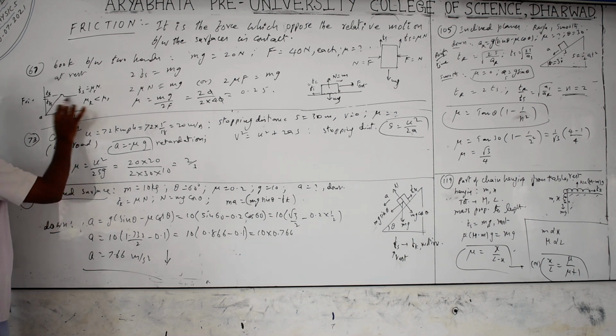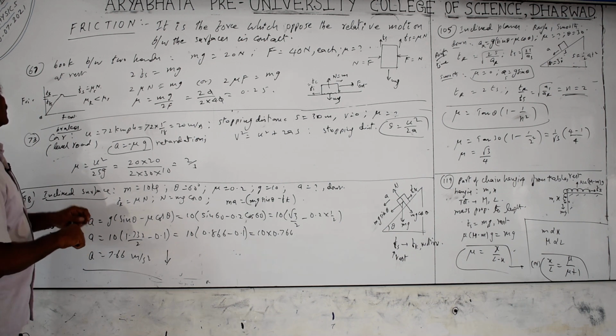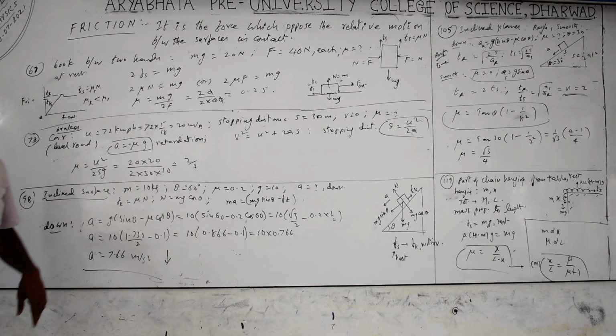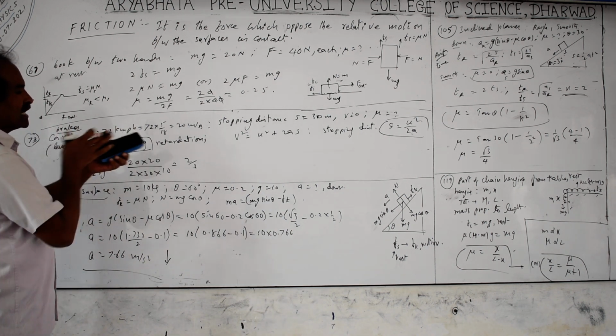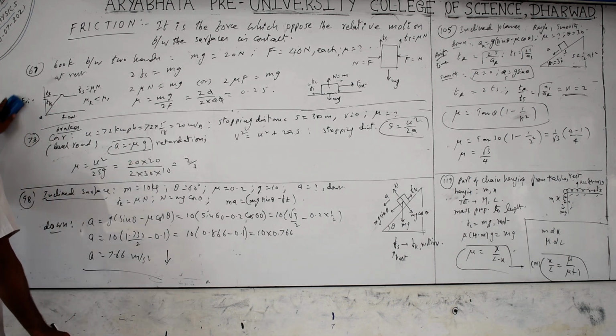And the frictional force, when the object is in motion, does not depend on the velocity, and friction does not depend on the surface area. These points are important ones. And this is provided the velocity is not too high. If the velocity is too high, due to the roughness of the surface, heat is produced, and thermal locking takes place at high temperatures.